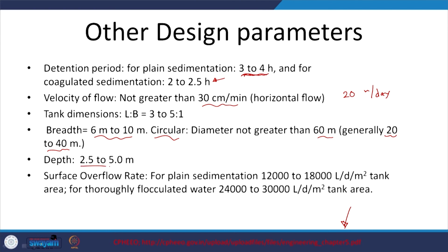You do not want to have a very low depth, even though the design says that your sedimentation will occur within a relatively less depth. You do not want very low depth, especially in rectangular tanks. Why is that? Let us say the flow comes in relatively higher, then what is going to happen? You can have scouring, that is not what you want. Also, if you have greater depth, the particles will experience more flocculent settling. So, that is one aspect to keep in mind, flocculent settling.